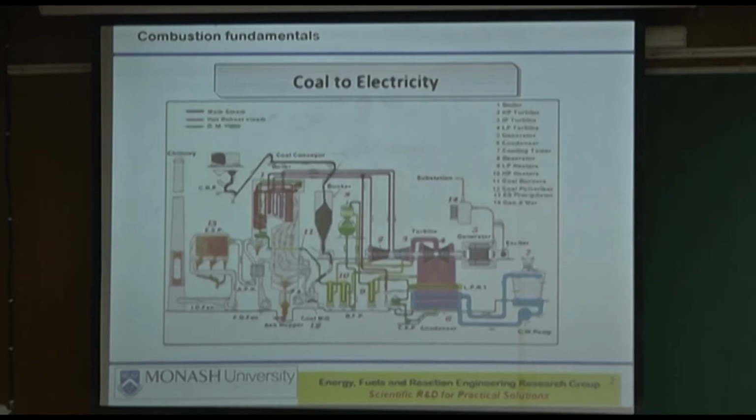Therefore, pre-drying the coal to the right moisture level and milling it to the right size is extremely important, because you have designed your boiler accordingly, and all of a sudden, 2 years down the track, a new mining company comes, the operators change, and they say, oh, I don't care about the boiler anymore, I'll just do it as simply as I can. They start milling it to a coarser size, they start pre-drying it to a lesser extent, and the boiler gets buggered completely.